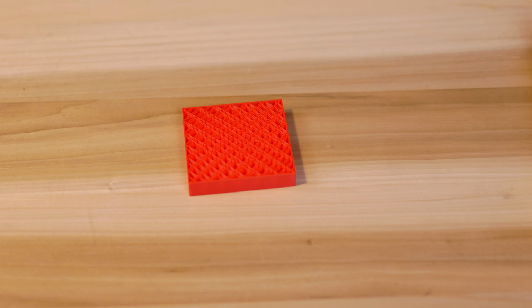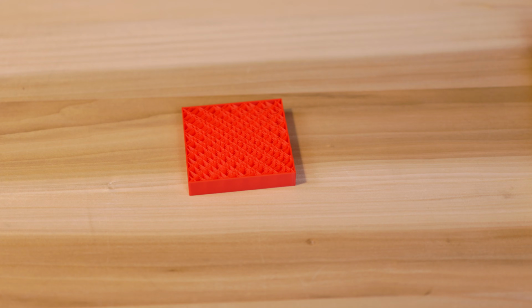All right, next on the list is line. The description for line is parallel lines without alternating directions per layer. The use case for this would be for simple parts with minimal strength requirements. The pro of this is it's faster to print. The con is it has the least internal support. This is best for draft prints or non-functional parts. That's the printing tip. This took 1 hour and 3 minutes and used 68.75 grams of material for this particular cube.